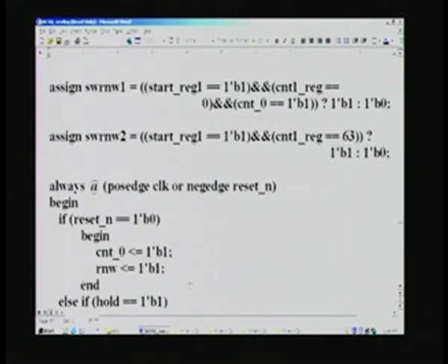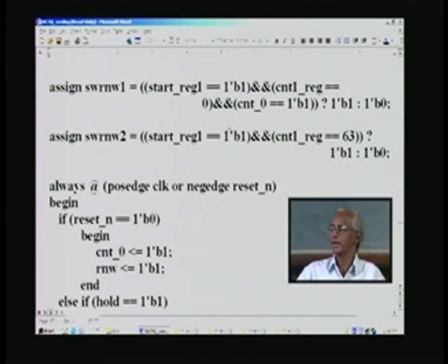So here what we need is to differentiate between the very first block of processing and subsequent blocks of processing. That is possible only by having one signal here, and it is just a single bit. It is initialized to 1 at power on, and this is meant for changing the R and W signal. Suppose you have written the very first block; after that we have to change this R and W signal, and this is so only after writing the very first block.